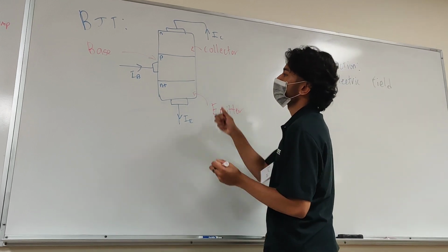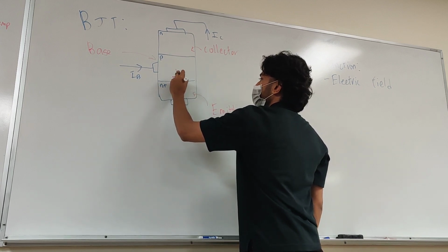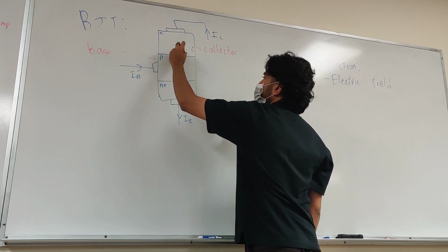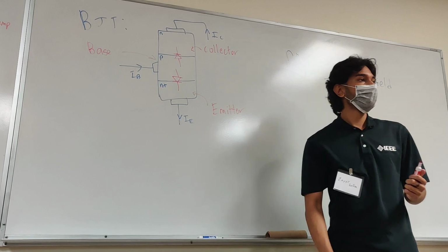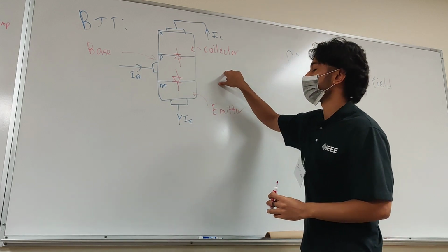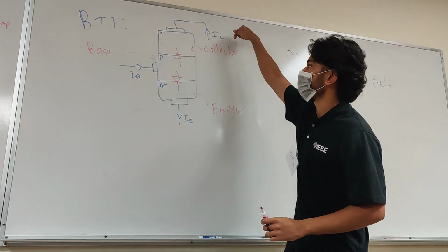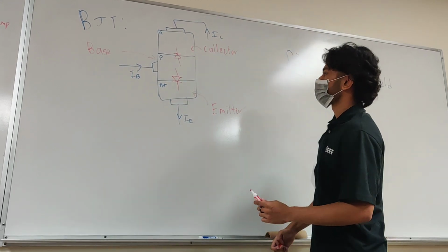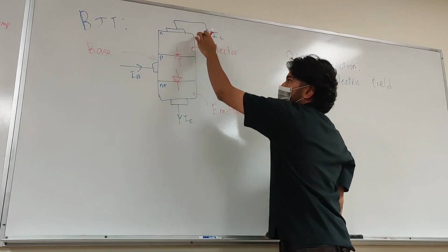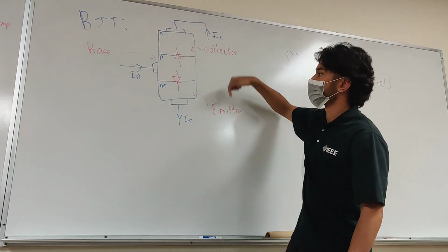Now, if you look kind of carefully, see this is a p-n junction, right? This kind of acts in a way like the same diode over there. Same for this. Right? Good so far? So what happens here is that we want, generally speaking, to be able to tweak this area here and to get a resulting change over here in the current. Because what's happening is we want current to primarily go from here to here. This is our main output. So ideally, we want to modify the voltage here and get a change in current.